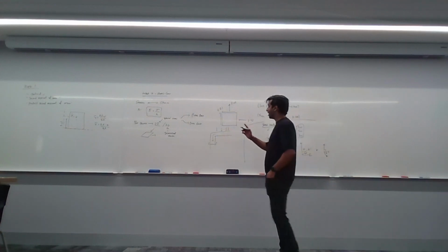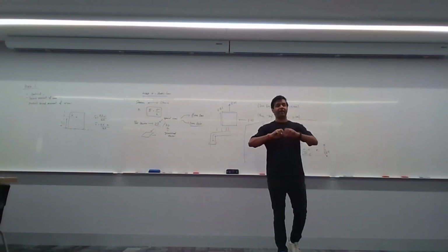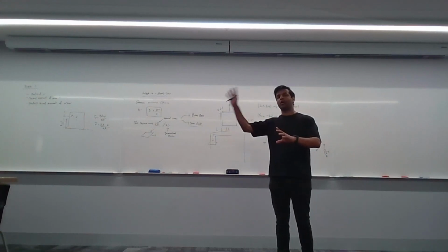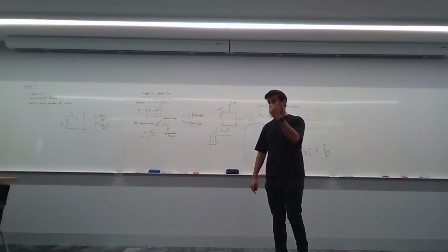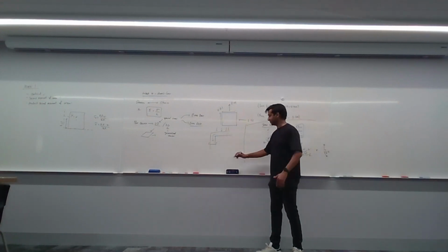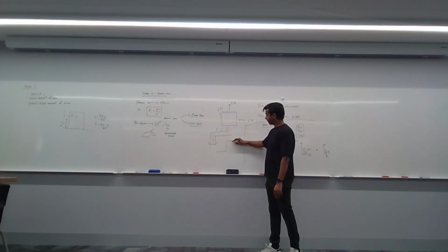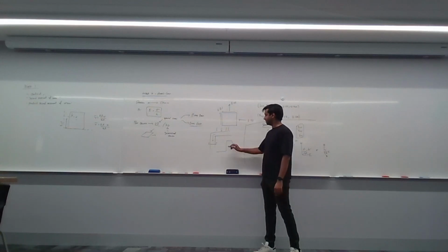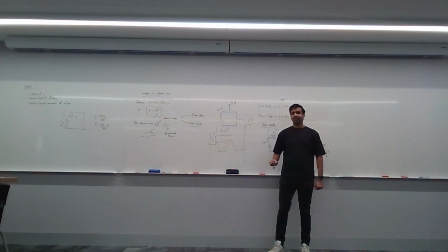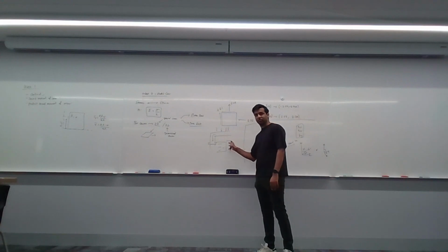Now, how do you identify plane strain? Plane strain is most common when you have an object or a structure that has an indefinite length or a very long length in one direction. I'll give you an example. A retaining wall that runs into the page for however long distance. Or like a dam. So you have a dam here like that, and it is holding back all of this water. The dam runs into the page for a very long distance. It's holding back all this water.